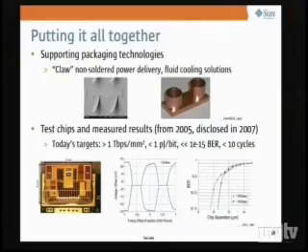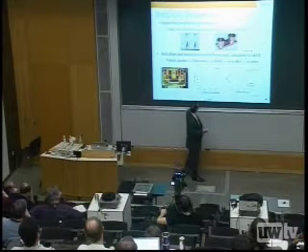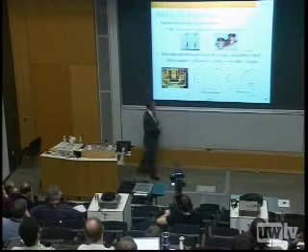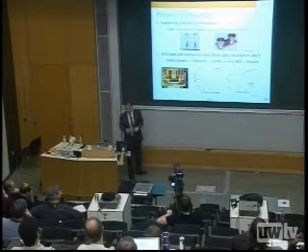Okay, what have we done? We built a chip in '05 and talked about it at ISSCC in '07. This is actually a relatively old chip, in a 180 nanometer technology at 1.8 volts. It does 1 terabit per second per square millimeter of chip space, so it's a pretty efficient I/O channel. You can't read this, but this is the RX and that's the TX. Those squares are the arrays of proximity communication, relatively small. It does under 1 picojoule per bit for communication, with a latency that's relatively small and a very low bit error rate.